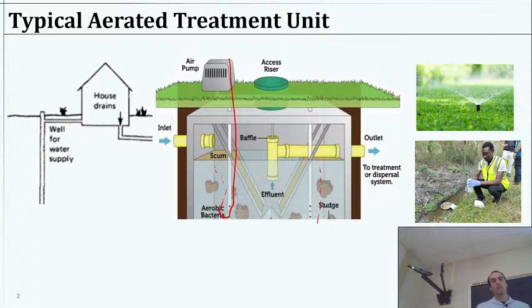We will get scum on the surface, undoubtedly, especially with all the bubbles, but we could put in this baffle here to stop that from approaching the effluent. So the entire scheme here is: we have wastewater discharging in, we've got aeration in a fair portion of this little tank, and then we have a space where we can have sedimentation.